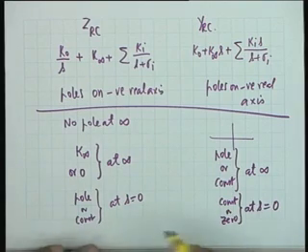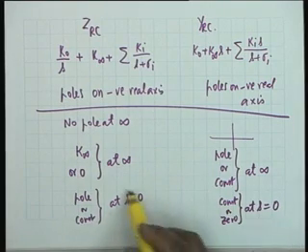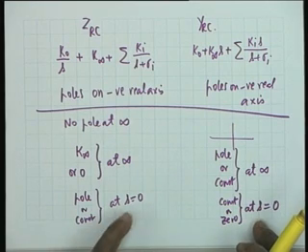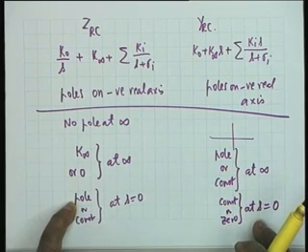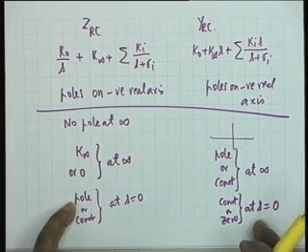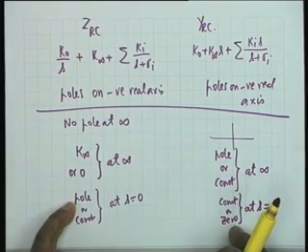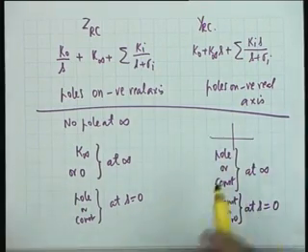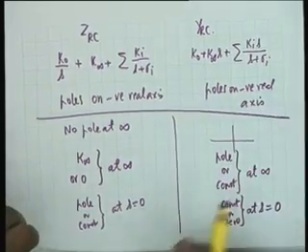Well, if you look at the properties of ZRC, this property of YRC is obvious. If ZRC has a pole at infinity or at s equal to 0, obviously YRC has to have a 0, right. So, it is a reciprocal property, but nevertheless we list them out separately.